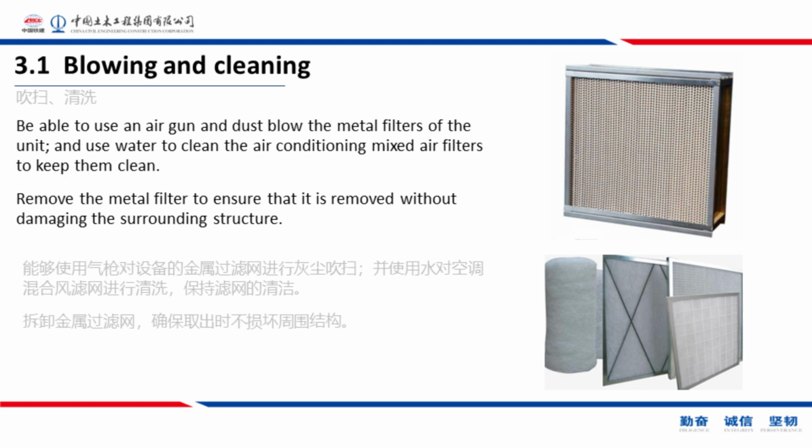PPT 26. 3.1 Blowing and cleaning. Be able to use an air gun to blow dust off the metal filters of the unit, and use water to clean the air conditioning mixed air filters to keep them clean. Remove the metal filter to ensure that it is removed without damaging the surrounding structure.